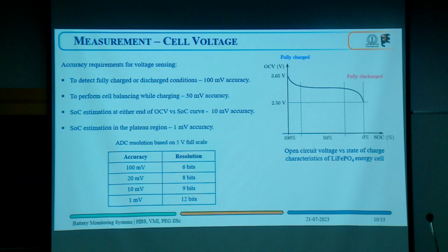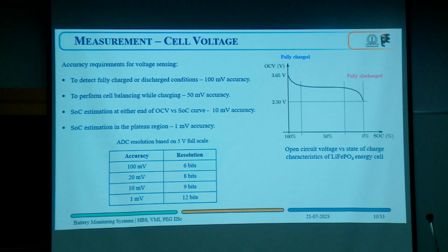But then what I can do is put a mux, and select which voltage I want to send. So again I have 5 cells, but now I have a selector here. It has 5 terminals, or 10 terminals if you want to measure differential voltage, and here it will send out only one signal.